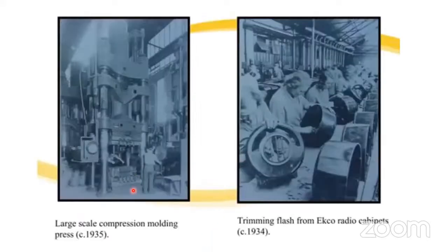See now here, this is a compression press, and these are the articles. These are the operators. Each has one machine here, and the jigs are here, right? They have removed the article. Now there are a number of flashes, right? Now they are removing the flash by knife. See now here, everybody is removing the flash. These are the new articles, and they are just checking the flash.